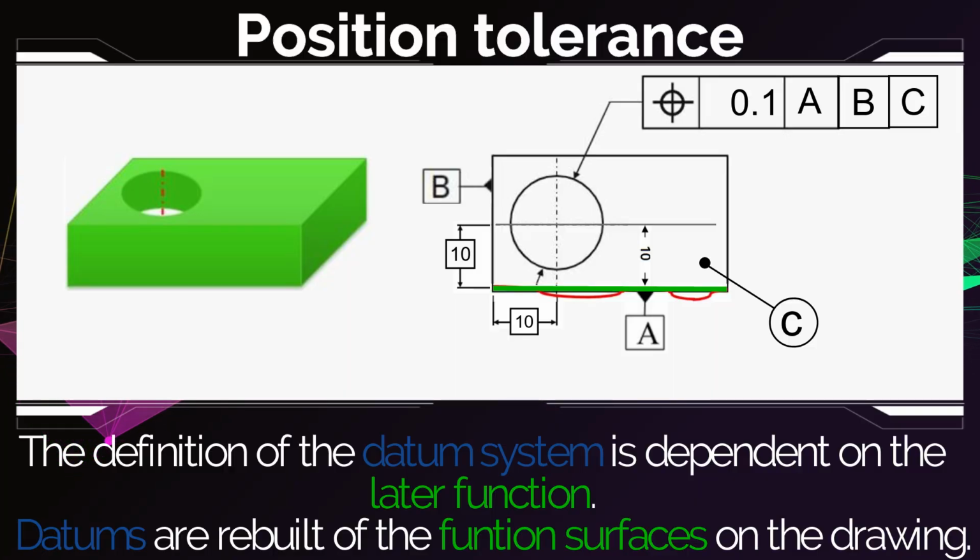To summarize, we saw that position saves cost by allowing more tolerance zone without negatively affecting the function. We saw that it simulates the function and assembly of the part during the measurement rather than just giving a random result. Also, using position means that you control the form of the element and the orientation, because the tolerance zone has to be parallel to the datum. All of these advantages for using GD&T over just a size dimension to tolerate location make it extremely important to consider using position whenever there is a chance.